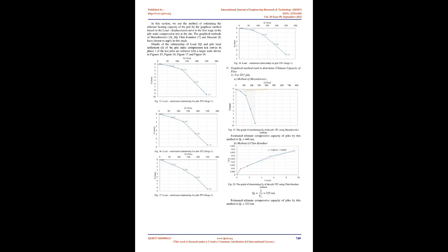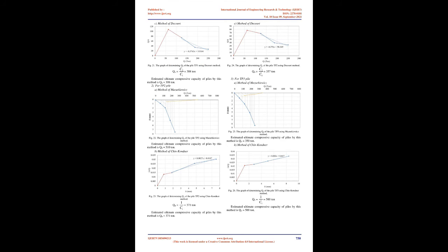Determine pile capacity. The objective of the research was to calculate the bearing capacity of a single pile based on several conventional methods. It is obtained based on soil investigation in the field: the SPT value, liquidity index, boring log, and data for one location from some points of observation, and the analysis of the bearing capacity of the single pile and its settlement based on loading test data.